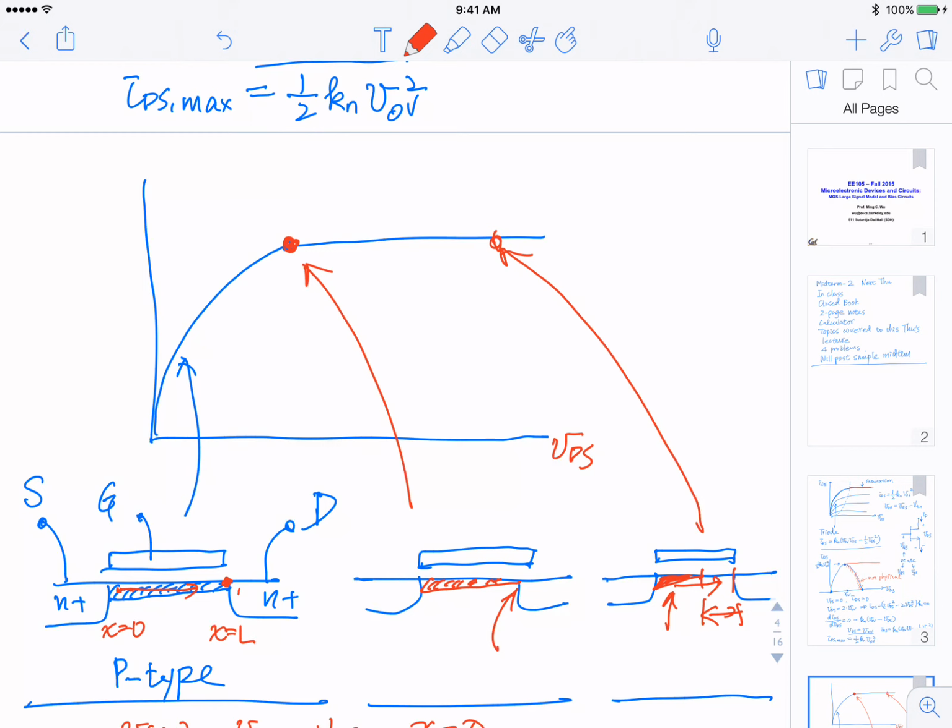These electrons will continue to be accelerated through the high field region where there's no charge. I describe it like a waterfall. Initially there's a slow, gentle slope. The river is coming down with lots of water, and then you go through a waterfall where it drops a lot of voltage, and the water just drops down. So there's no accumulation of steady state charge, but there are a lot of charges flying by.